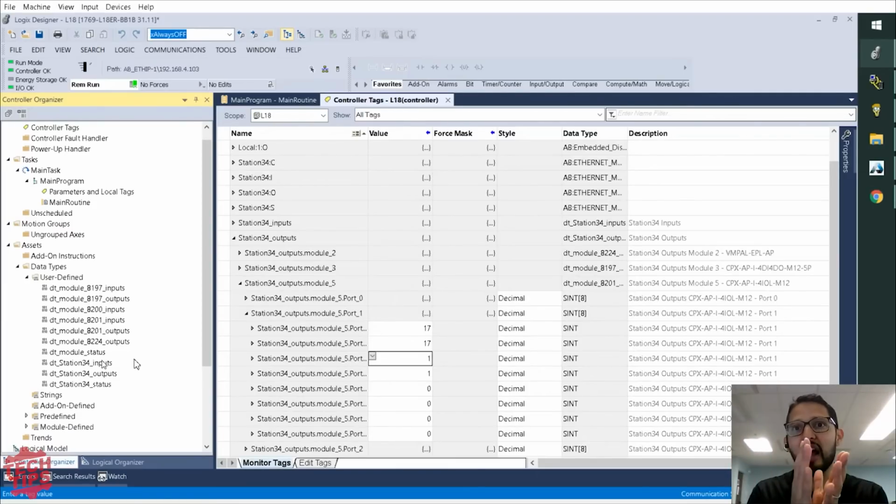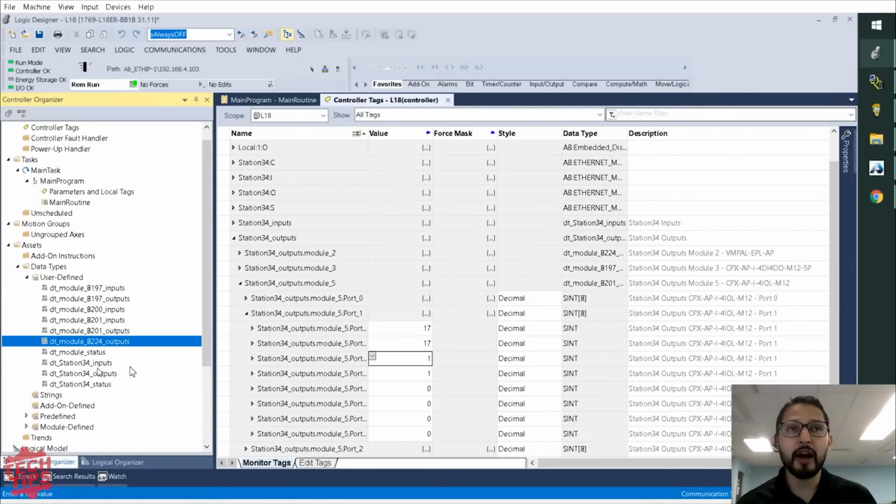Because if you don't make this modification, then all of your modules are going to be offset by a byte or something, and we don't want that because a lot of times you already have 40 modules or something, and you don't want 40 modules to be offset. So basically, you go in here, you create an internal offset on the program, and that would be it. Then you don't have the problem with the mapping, and it's really simple to do this. So you guys have it documented. Like in a chassis, you just put a slot filler in.